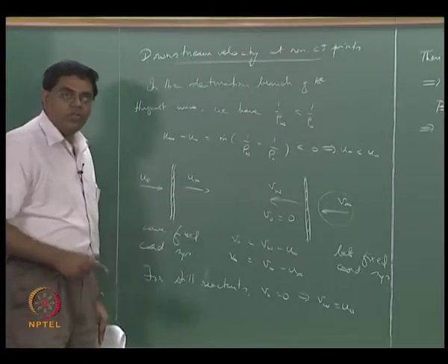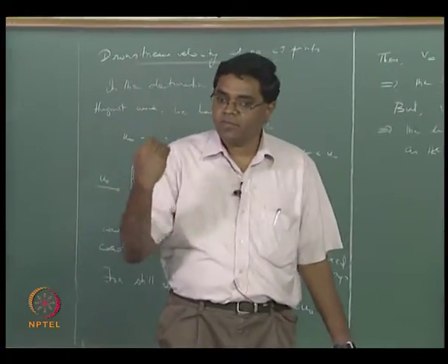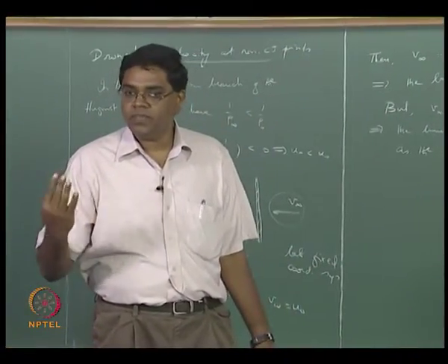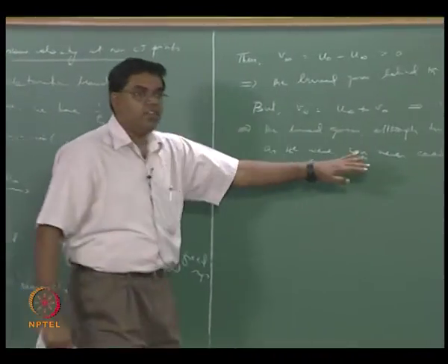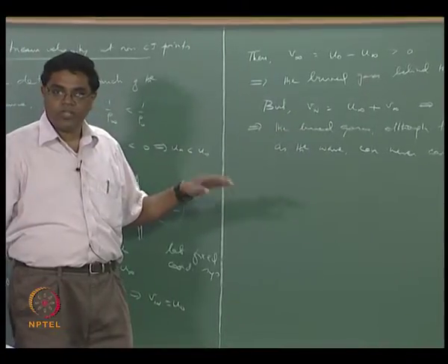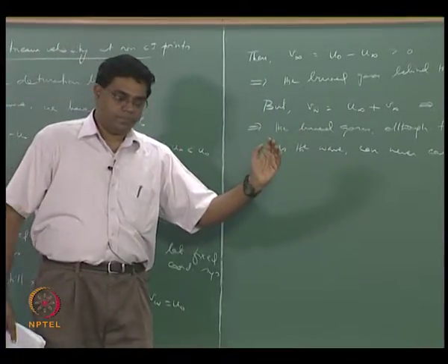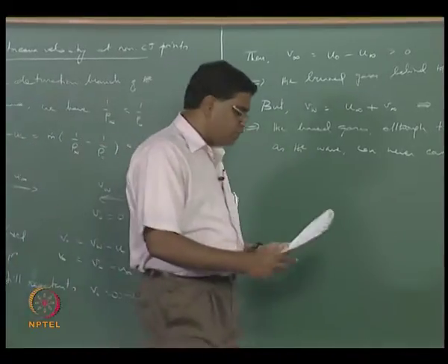So the downstream Mach number always would look like it can be lower. It does not mean that the velocities are lower, but what we are actually finding out here is the velocity is lower than the wave velocity. Therefore it's not going to be able to catch up. It follows, but it can't catch up.